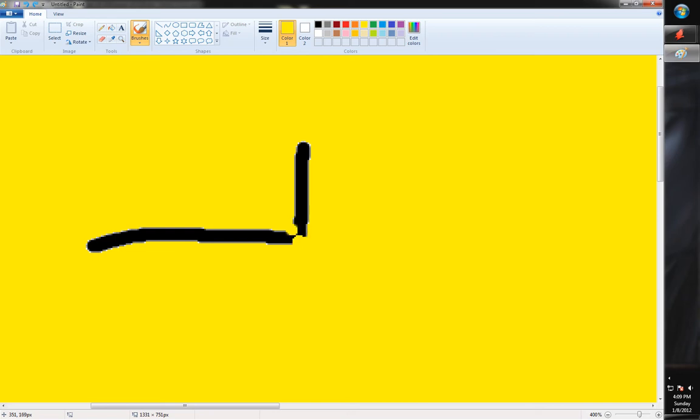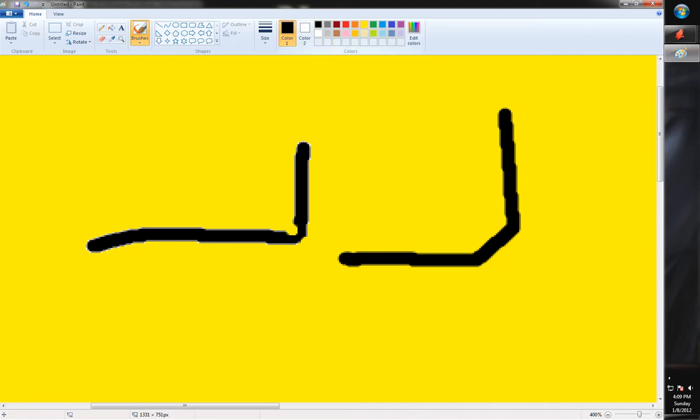And so that is why when we do 90 degree angles, we do a 45 degree angle. That way when the etching process comes in, it may take just a little tiny bit out of it as it goes up, and it's not going to be this huge problem like it is here. So that's why you definitely want to keep no 90 degree angles in your design. It's not too much for impedance. However, impedance is kind of an issue.